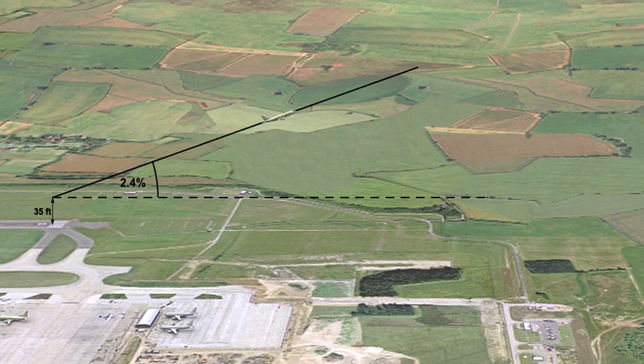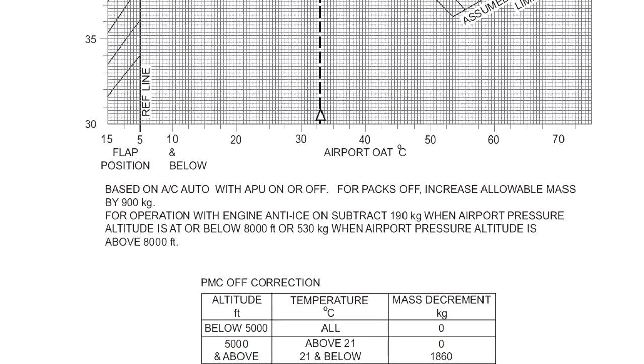In other words, if the mass of the aeroplane were greater than the climb limit mass, then the aeroplane may still be able to climb, but it will not achieve the minimum air gradients that the authorities have laid down. Try to remember that these gradients are air gradients and are therefore unaffected by wind. In order to help you calculate the climb limit mass, let's work through an example.